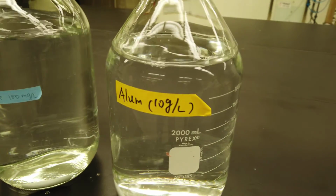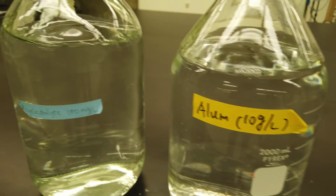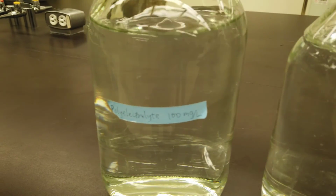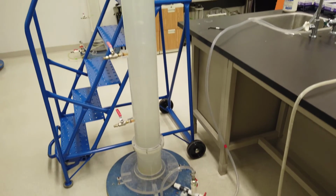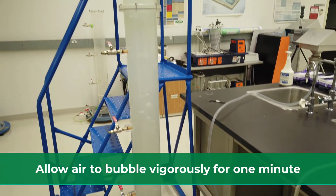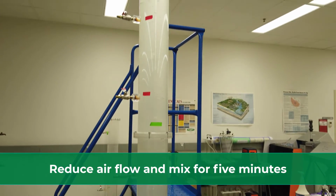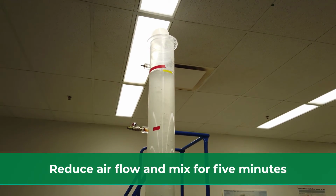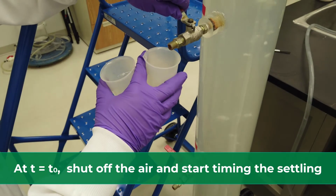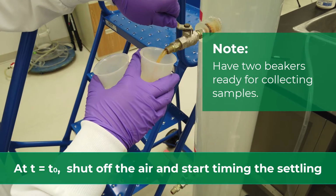The concentration of Al3+ will exceed its solubility limits, and aluminum hydroxide will precipitate, forming a dense flocculent suspension. Ensure that the column is uniformly mixed by allowing air to bubble vigorously for 1 minute after the addition, then reduce the airflow and continue mixing gently for a following 5 minutes. At time t equals t0, shut off the air supply and start timing the settling.